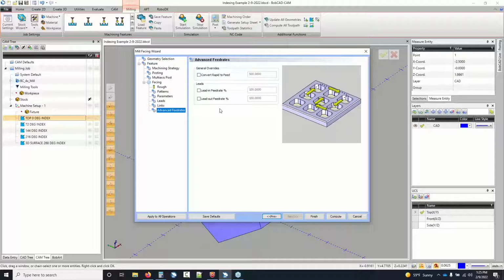So instead of the rapid move being a direct straight line across your part, you'll end up with an angled line that gets to the x-axis before it gets to the y. Basically, all your axes are moving as fast as they can. They're not clocking themselves to stay in a nice straight line like they normally would be with, say, a normal G01 feed move. When you go into a G00, every axis on some machines goes as fast as it can to get to the location.